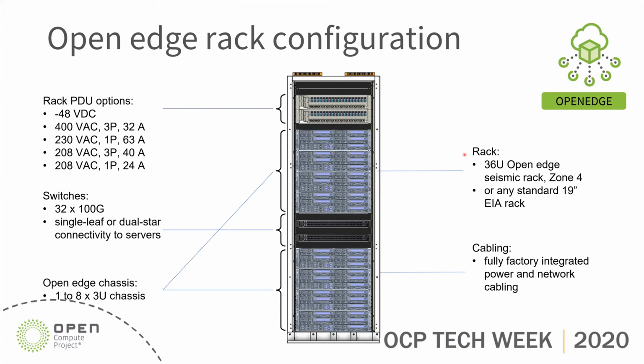The depth is only 665 millimeters, so easy to handle at the site, even at locations where the space is more limited and the door openings might not be high enough to accommodate moving in a 42U or even higher rack. So compact in that sense. It's seismic zone 4 compliant, so can be deployed anywhere.